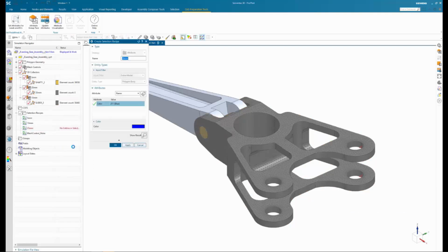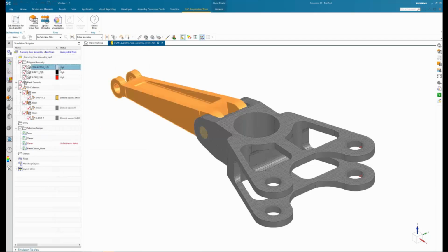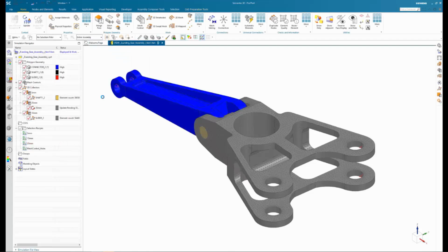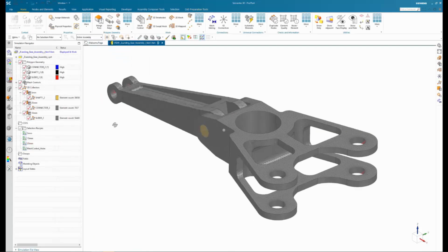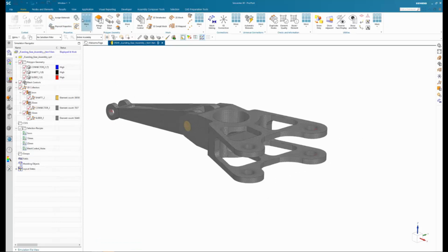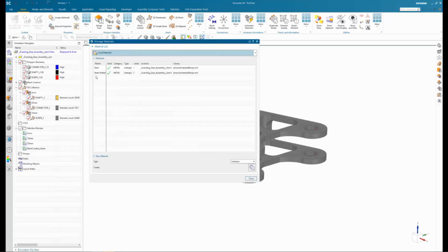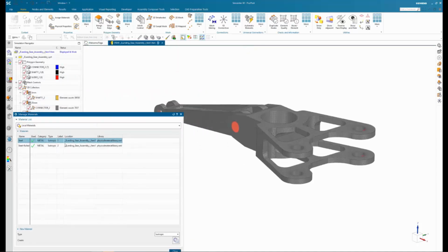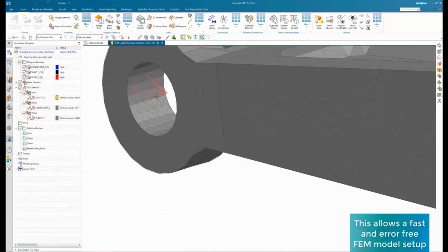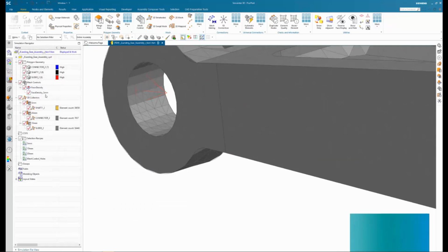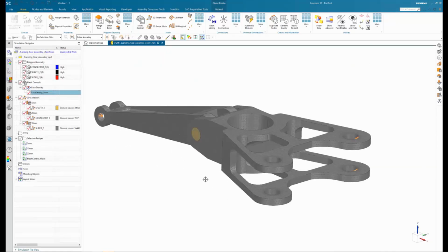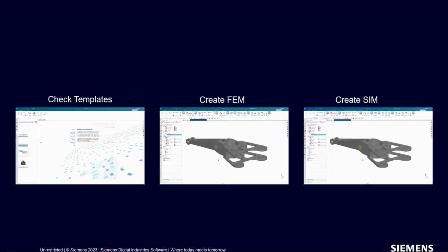If we look at that, it's going to look for bodies that are blue. So we want to change the color of that body to be blue, and we immediately see an update for our CAE model. We update the model, and now that last component is meshed with a particular element size. The materials are already assigned. Those materials were inherited from the CAD data, the material assignments on the CAD side. And we also see a face density. In a local area, I have a local mesh size throughout a number of the faces in the model.